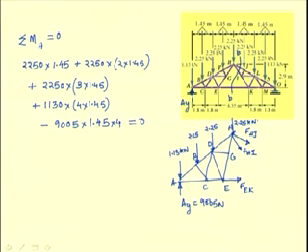And also we have the moment of this force EK, which is a positive moment, FEK, and the moment arm is 2.9 meters. So, the sum of all these moments is equal to 0, and from this equation the force in the member EK can be determined, and it is determined as 9000 Newton, and since it is positive, it is tensile in nature.